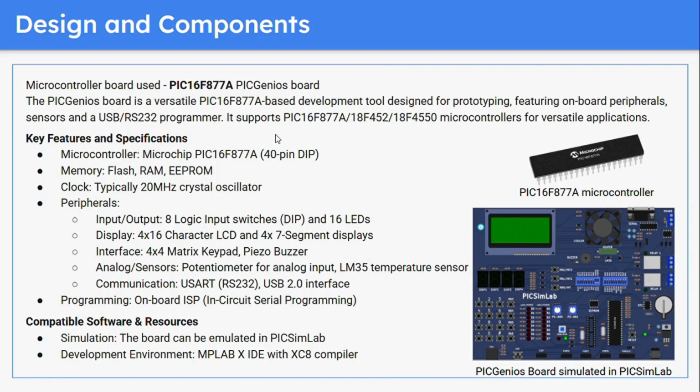It supports the PIC16F877A microcontroller. The key features and specifications are listed out over here. The board contains the main microcontroller, which is the PIC16F877A microcontroller. It is a 40-pin microcontroller. It contains memories like flash, RAM, and EEPROM. The clock is typically a 20 MHz crystal oscillator.